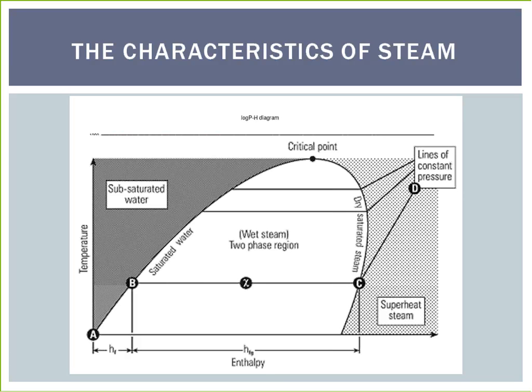The point at which the saturated water and saturated steam lines meet is known as the critical point. As the pressure increases towards the critical point, the enthalpy of evaporation decreases until it becomes 0 at the critical point. This suggests that water changes directly into saturated steam at the critical point. Above the critical point, the steam may be considered as a gas. The gaseous state is the most diffuse state in which the molecules have an almost unrestricted motion, and the volume increases without limit as the pressure is reduced.